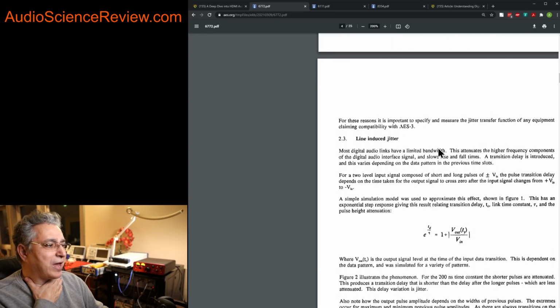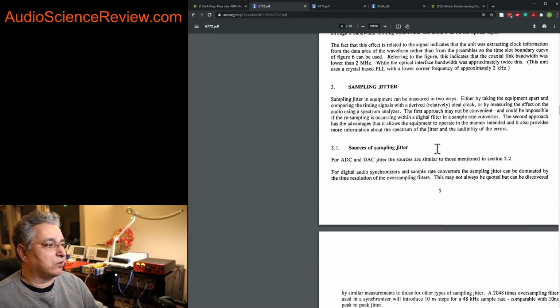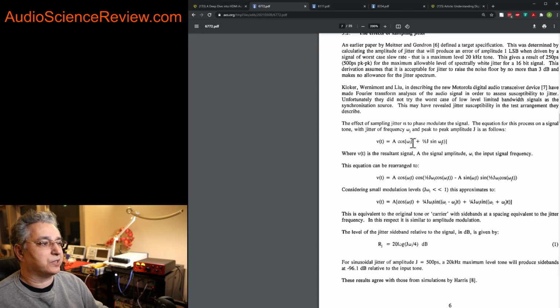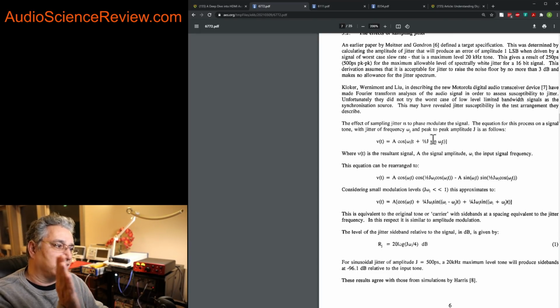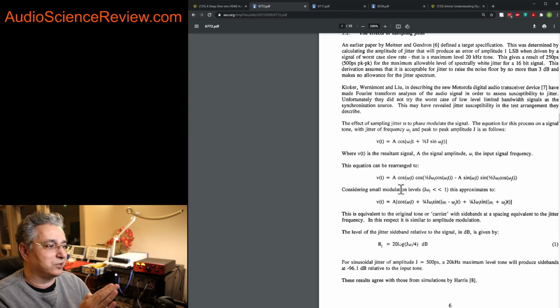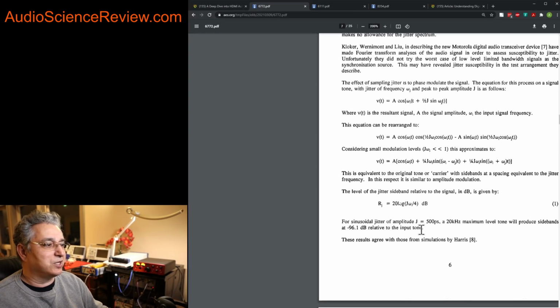But he did a simple math. He took the mathematics of jitter, which is sinusoidal, assuming you have a sine wave and you mess up its timing with another sine wave. Basically what happens is that the phase of that sine wave gets modulated yet again. This is a gnarly formula to try to resolve, and I'm not going to walk you through it, but you can read the math. But he's done some simplifications, and turns out you can predict the interference that you get from jitter, and it just becomes proportional to the frequency of your source signal.